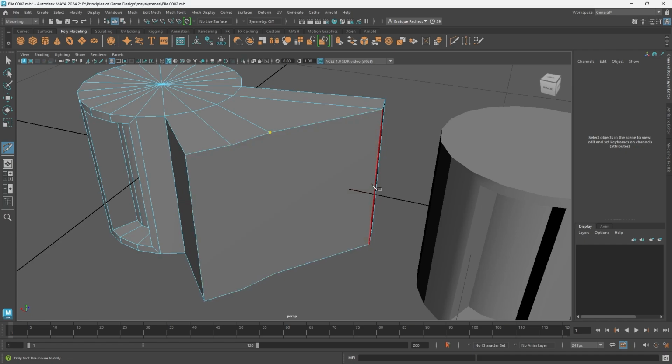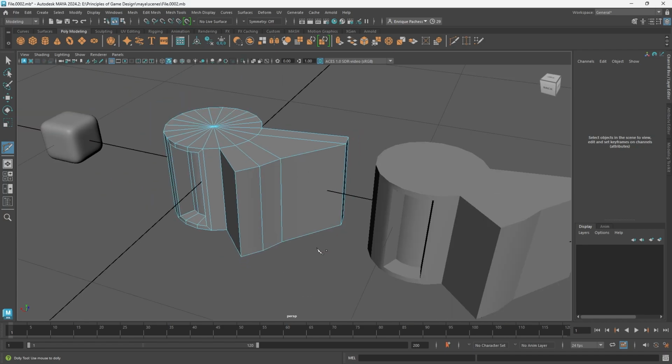You can then click and drag on any other edge on that same polygon and create an edge by hitting the Enter key. You can also go ahead and cancel by hitting the Escape key. So with the Multicut tool's functionality, we can click and drag and create the edges that we want to break up our n-gon.